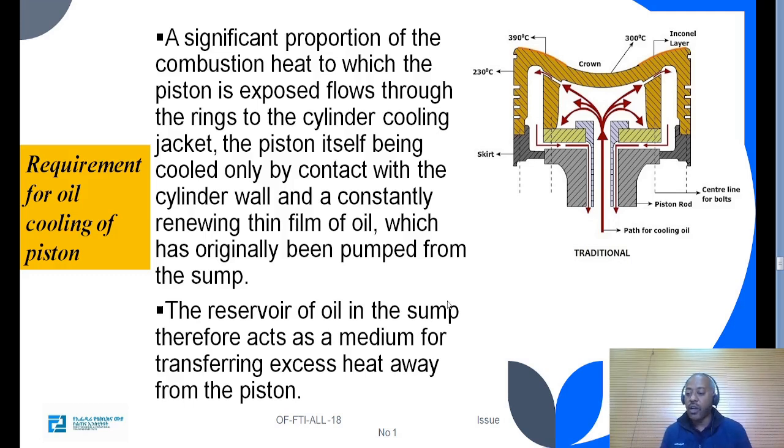Requirement for oil cooling of the piston. A significant proportion of the combustion heat to which the piston is exposed flows through the rings to the cylinder cooling jacket. The piston itself is cooled only by contact with the cylinder wall and a constantly renewing thin film of oil, which has originally been pumped from the sump.